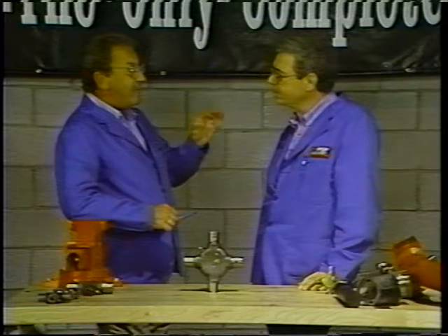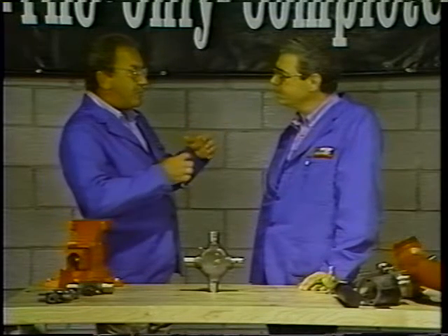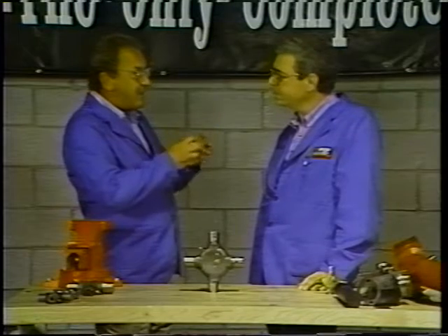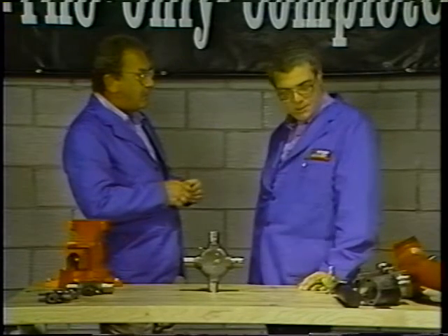by bit. Now, I also heard of one-position surface spalling. How does this differ from what we've just been talking about? Well, Bob, that type of spalling occurs when a needle roller becomes lodged between a trunnion outside diameter and the bearing cap inside diameter. I see.